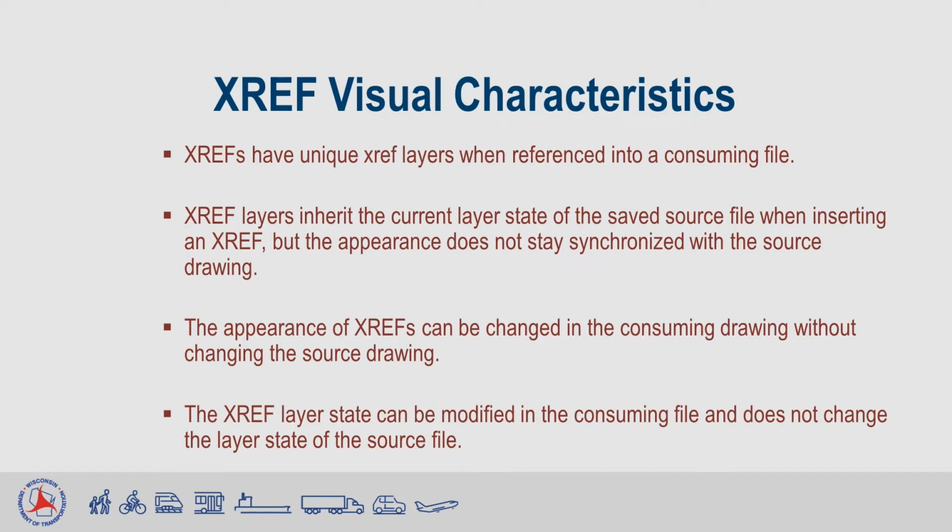Some things to note about the visual characteristics of an XREF. XREFs have unique XREF layers when they're referenced into a consuming file. XREF layers inherit the current layer state of the saved source file when they're inserted into another file, but the appearance does not stay synchronized with the source drawing. The appearance of an XREF can be changed in the consuming drawing without changing the source file, and the XREF layer state can be modified in the consuming file, and that doesn't change how it appears in the source file.